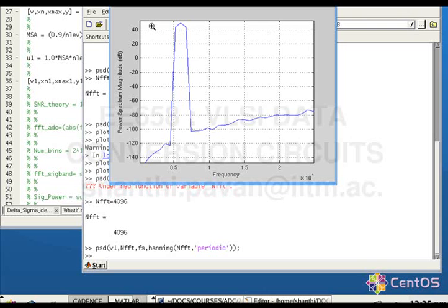The only difference between an oversampled converter and a Nyquist converter is that in the Nyquist converter, the signal to quantization noise ratio is measured in the following way. You find the signal power, right? And everything other than the signal bin is quantization noise. So you take the ratio of this power to that power, and then you do dB and all this other stuff and get whatever number you get.